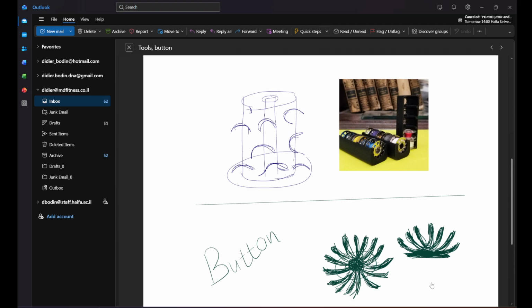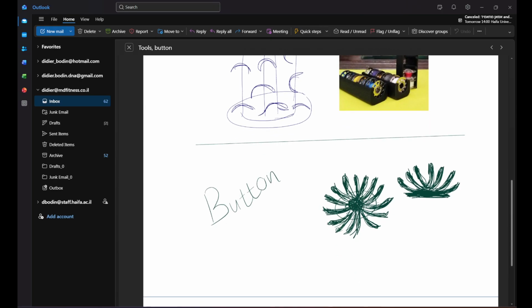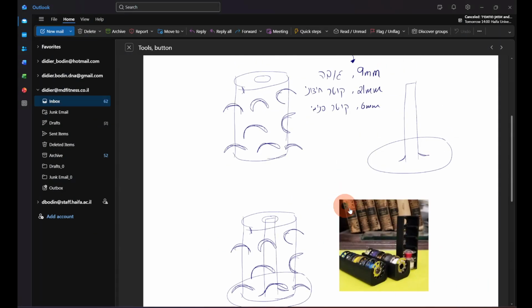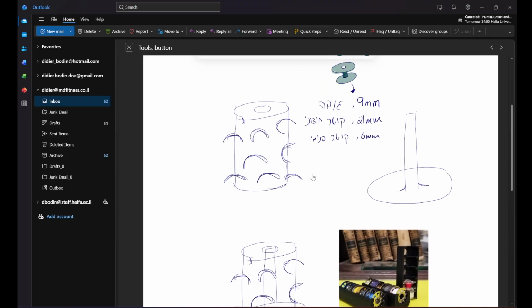And there is a function to multiply, to pattern the shape. It's called circular patterns that we can use. Just checking that we're recording, yes. Okay, so if we want to build something like that, we're going to first build the stand using revolve, and then we're going to build this piece above it, also using a mix of revolve and cut.